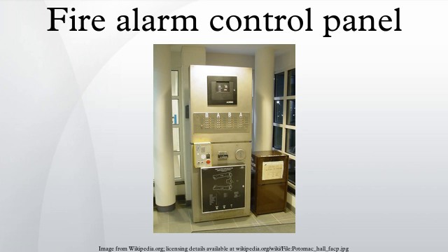Depending on the system's layout, the NACs may or may not activate for pre-alarm conditions. In a two-stage system, the NACs are typically coded to a special first-stage coding, or in some situations where a loud alarm signal could be disruptive, chimes will activate. If there is a voice evacuation system, it will usually instruct building occupants to await further instructions while the alarm is being investigated. Priority to alarm, also known as security.